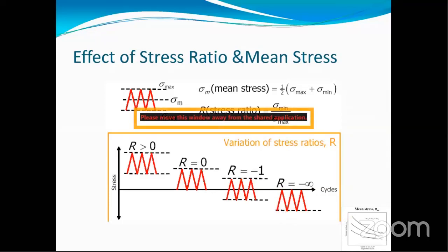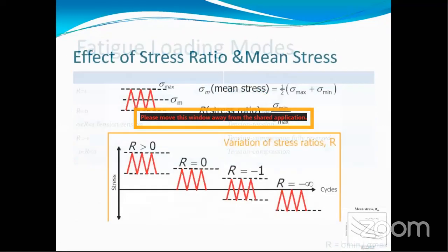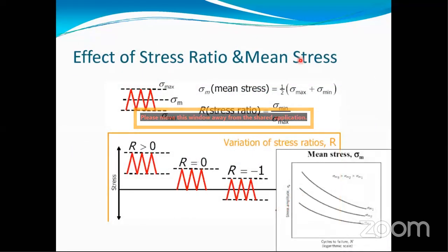And we can even see here we have a significance of the mean stress. Here there is a lot of significance to mean stress. Positive mean stress tends to bring down the fatigue life, and negative mean stress tends to increase the fatigue life. That's why we generally aim to increase the fatigue life by seeing that mean stress is as low as possible. Here we can see all these things from these curves. We can observe the same pattern.